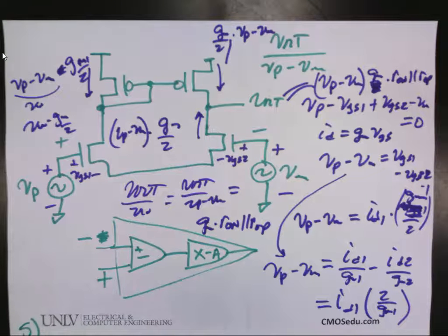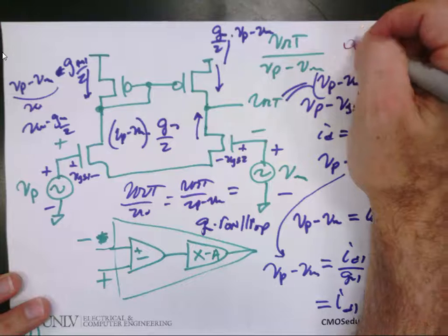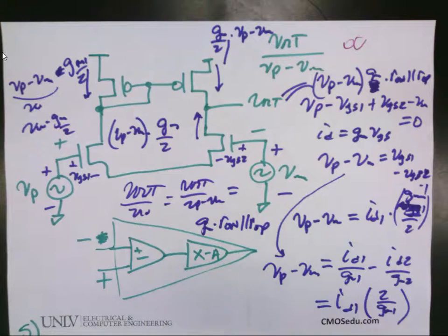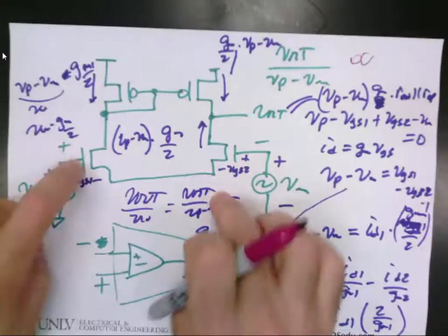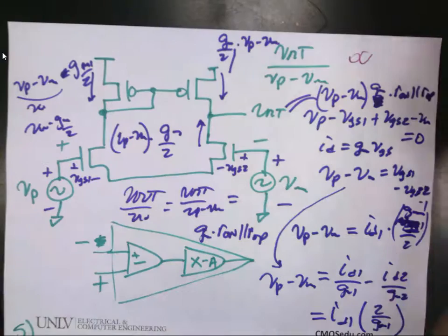Like, does anybody know what LVDS is? It's used in your cell phones, for the communication between the CMOS imager and the image processor, or the DRAM and the processor. It's low voltage swing, differential swing, where one of them's going up and the other's going down. So if there's any noise on the two lines, it gets rejected by the common mode rejection of the op amp or the input. So that's what I'm about to talk about. So it's not academic crap. This is useful.